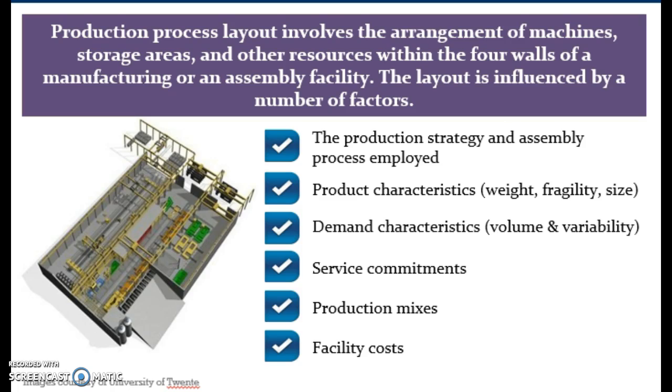One of the key drivers of how production activities will be carried out is facility layout. Facility layout involves the arrangement of machines, storage areas, and other resources within the four walls of a manufacturing or assembly facility. An appropriate, successful layout is one that does the following: reduces bottlenecks in moving people or materials, minimizes material handling costs, reduces hazards to personnel, utilizes labor efficiently, increases morale and ease of supervision, utilizes available space effectively and efficiently, provides flexibility, and facilitates coordination and face-to-face communication.